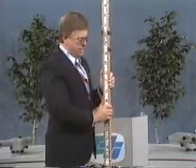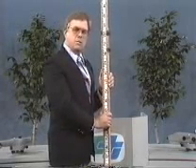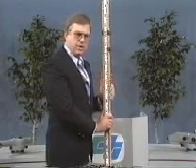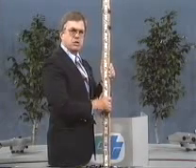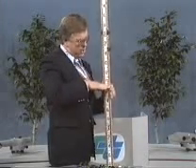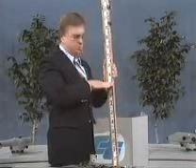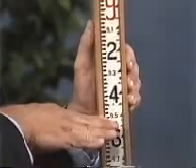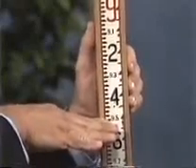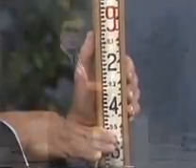For example, if you took the rod and you set it on a point that was higher than the original benchmark, that would raise the rod, which means that the elevation should be higher. So if the line of sight was at 910 here and you raised the rod, so if you're reading at, say, a half a foot higher, then you'd be reading at 910.5 instead of the 910 that you started with.